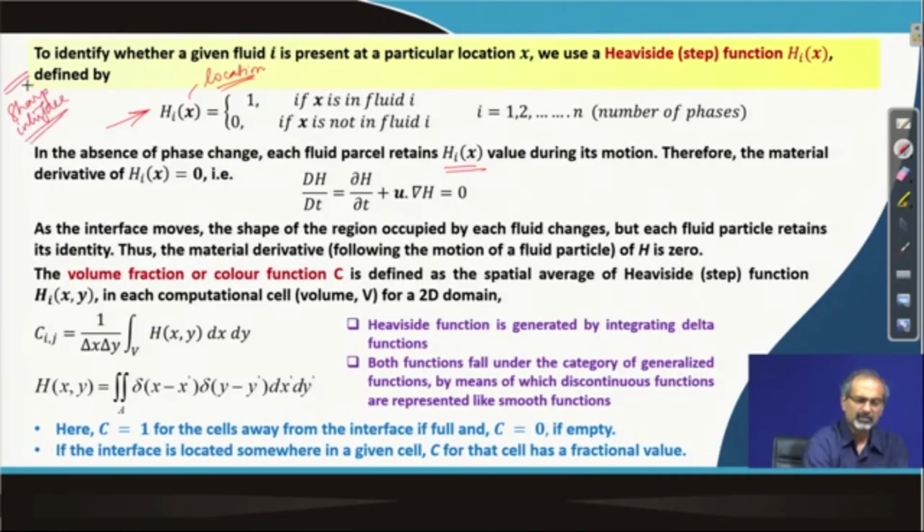Now, since we are discussing one fluid model where we are actually going to take the route of diffuse interface, we are not going to perpetually carry through the concept of Heaviside function, but when it comes to implementation, we will change over mainly to marker functions, but those marker functions will depend on how we connect them with the Heaviside function description, which is nothing but the sharp interface description of the problem. So, that dependence always has to be kept in mind.